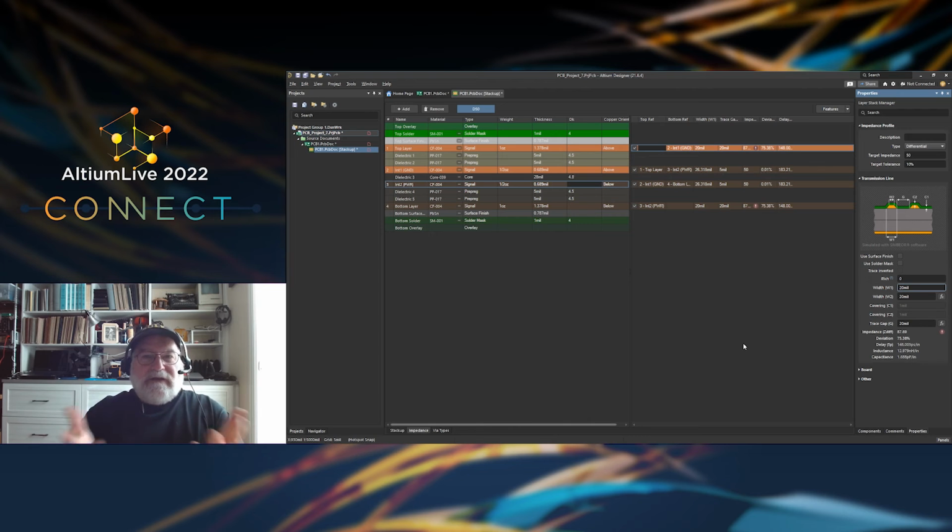The other way of using this tool is by synthesis. If you have the stackup from your fab vendor, so here's the stackup from our fab vendor, we're going to ask, okay, given these dimensions, and given the spacing between the two lines, what is the line width we need for a target impedance of 100 ohms?